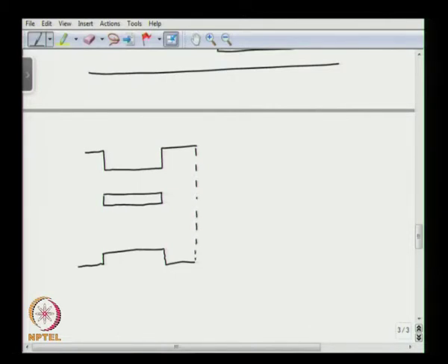Okay. So, this is P star plus delta P, this is P star. These are two channels, this is channel 1, this is channel 2, they are connected in parallel. This is R1, the resistance, and Q1 is the flow rate, here is R2 and Q2. So, we can write the total flow rate Q is going to be Q1 plus Q2, right.